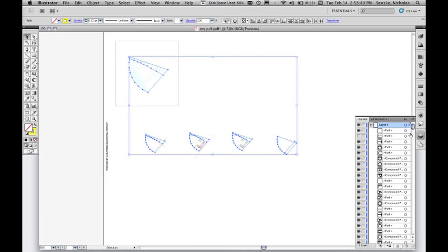Now again, they're not layered by what they are. They're layered by the pen type. And this makes it easier, because when you plot this for the first time, you're going to kind of hate what you see, because the plotted stuff is not the same as what's on the screen. But then it's going to be so easy to adjust, because all of the grays are the same layer. All of the blacks with a certain line weight are the same layer. And then just making that adjustment is going to be very easy.